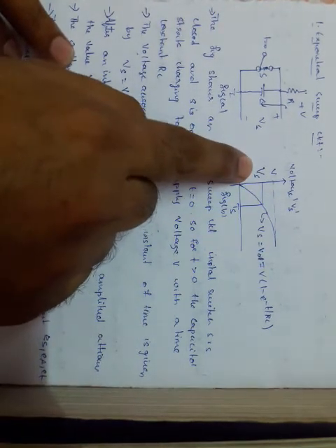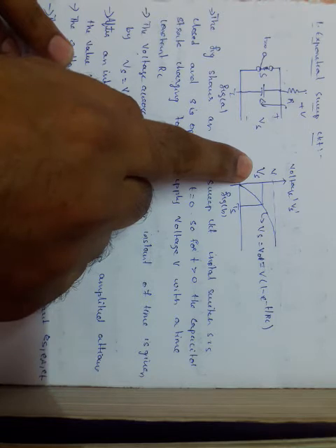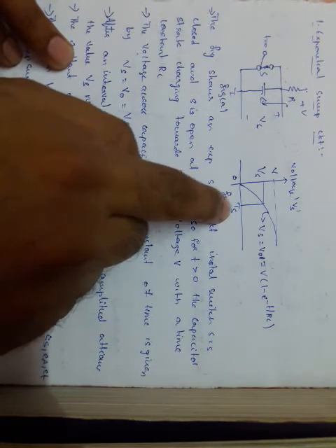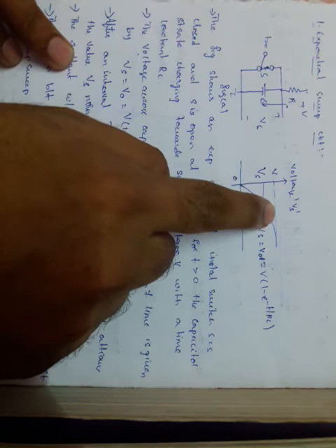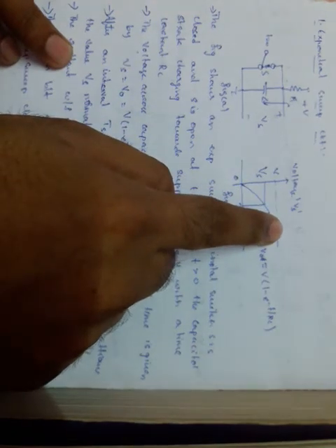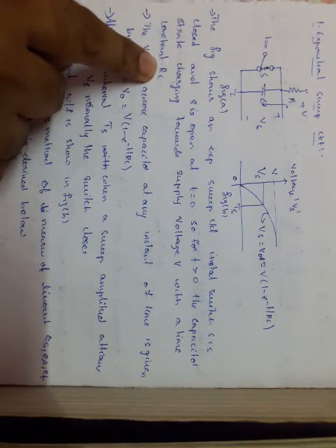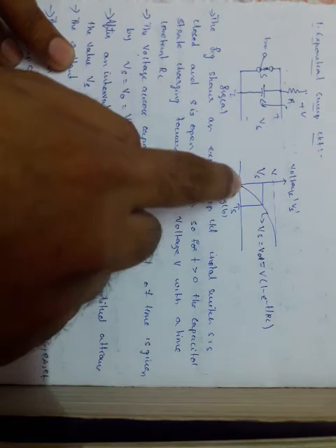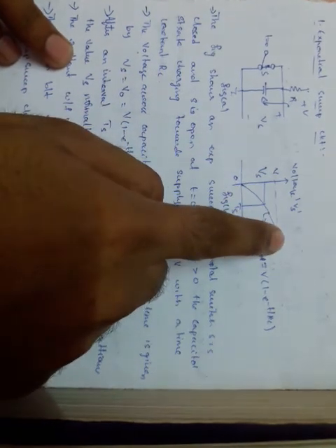We have written the voltage as Vs, that is the sweep voltage, and this is Ts, that is the sweep time, and it is exponentially increasing with a time constant T equal to RC, up to the maximum voltage. At the maximum voltage, the exponentially increasing sweep will be stopped.